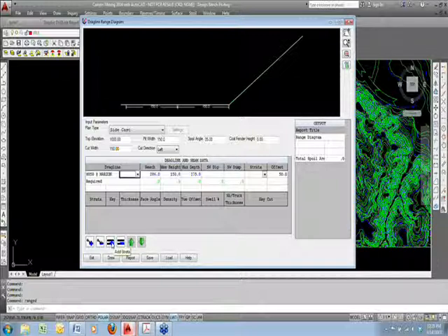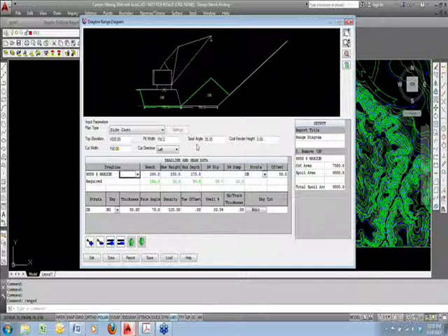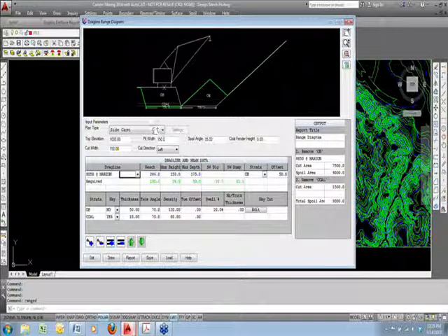So I'll just hit the first Add Strata button. And it instantly added a default thickness of 50. It called it overburden. And so we'll add the next strata below there. Coal, let's say it's about 8 feet deep, 8 feet thick.